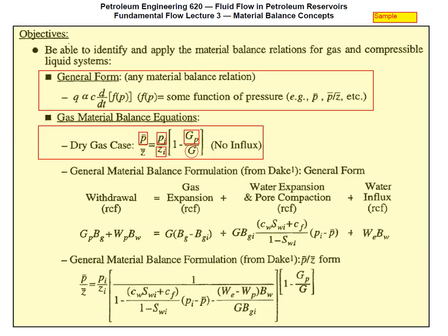Is 3 days enough to estimate average reservoir pressure, Santiago? No but. I like that. That's a perfect answer. No but. Not no space but no comma but. So what's the but? Okay, what happens if you use the average reservoir pressure estimated from a 3-day buildup? Is it too high or too low?